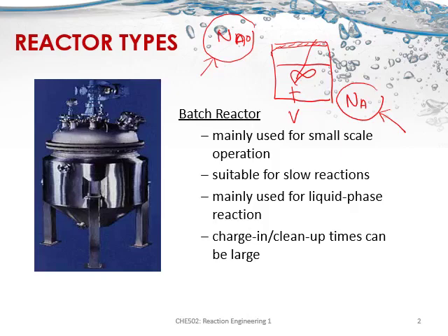Batch reactor is mainly used for small scale operation, suitable for slow reactions, and mainly used for liquid phase reactions. Charge and cleanup times can be large, so it may take some time to set up and clean up the reactor.